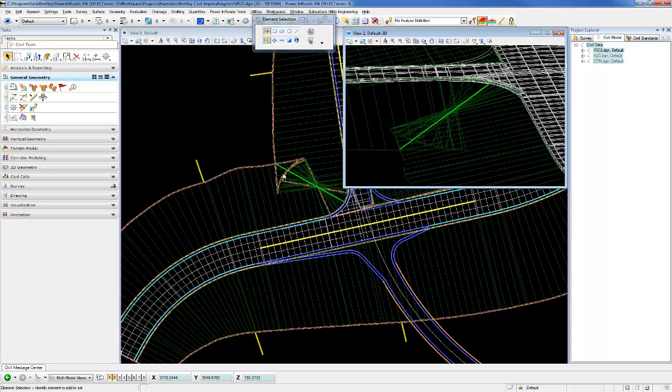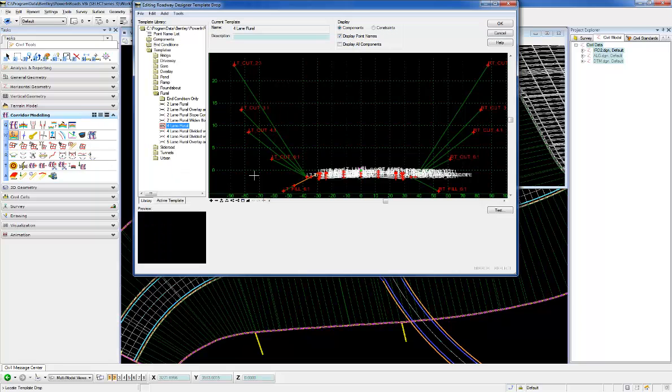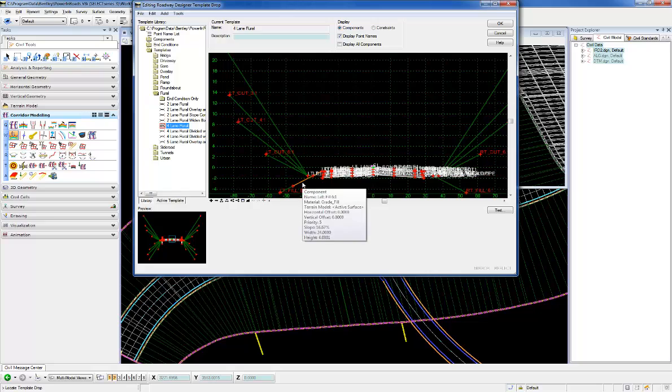Once I have the feature line drawn out here, that's going to give me a line that both of these slopes can intercept. So it can stop there. Instead of going over and overlapping, it's just going to stop at that point. And the way I've done that is in my template drop, actually. If I edit the template drops, I'll show that. I have a priority 1 in condition here.